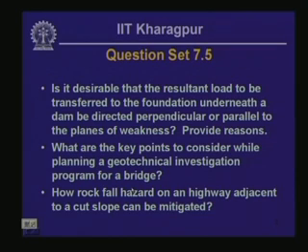So it is preferable that we have the orientation of the resultant of the load to be transferred perpendicular to the bedding direction, number one.